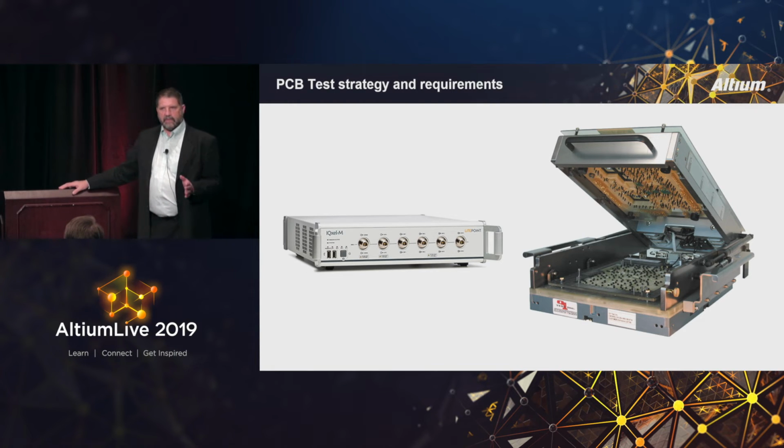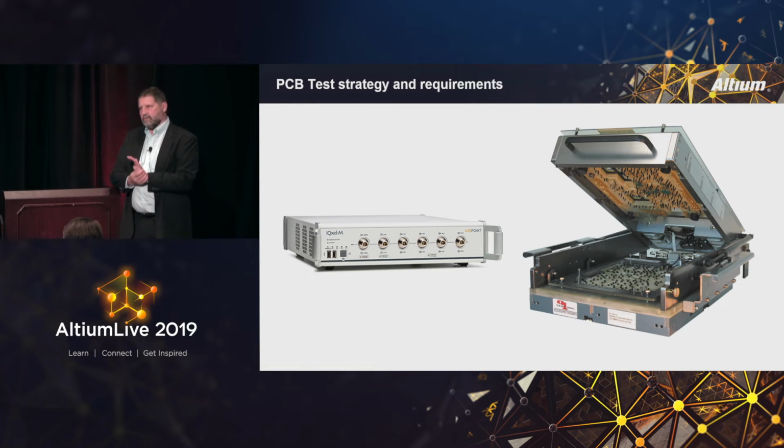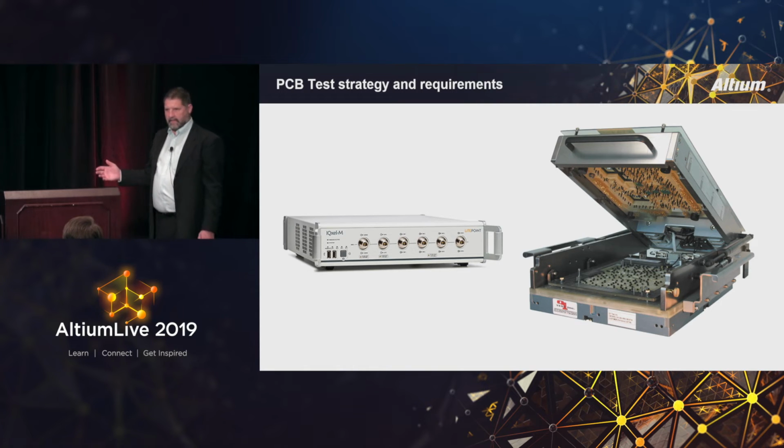The other thing that's a big cost driver is the size of the pins that you're using. So in affordability, if you're trying to use a 15 or 20 mil pad, that's going to be a lot more than using a 25 mil or a 1 millimeter pad. So 1 millimeter might seem like it's really big, but it will save money, and those probes are going to be a lot more robust.